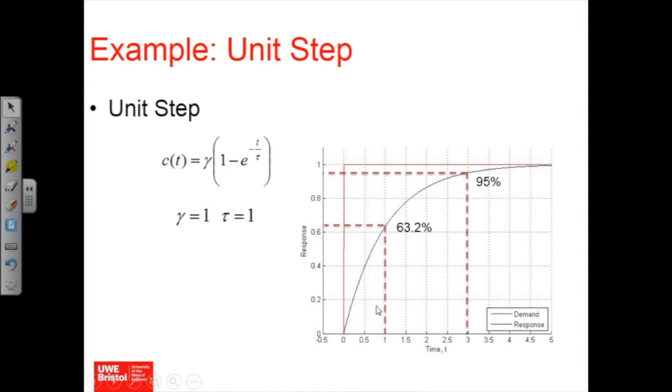Yeah, partial fractions, Laplace transform tables, and a bit of algebra, and we've got a time response for any, or all I should say, of our first order systems. Okay, so what's a first order system do? If I put in a unit step, it responds like that. What does it mean? Well, this number on the time axis is tau.